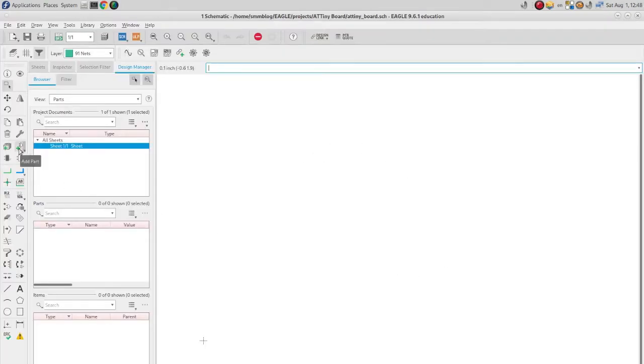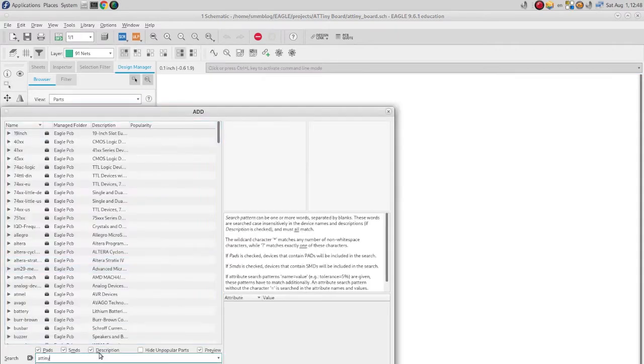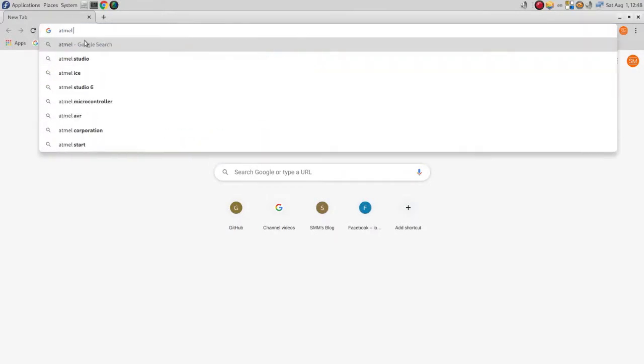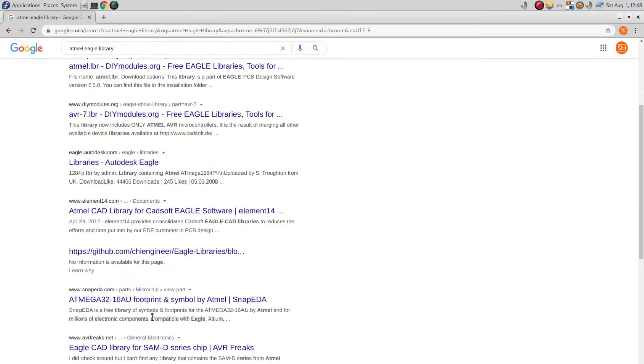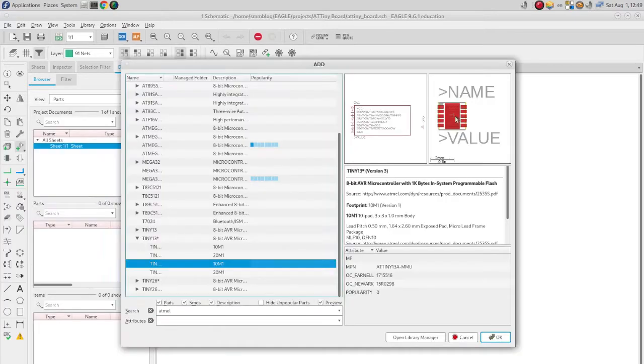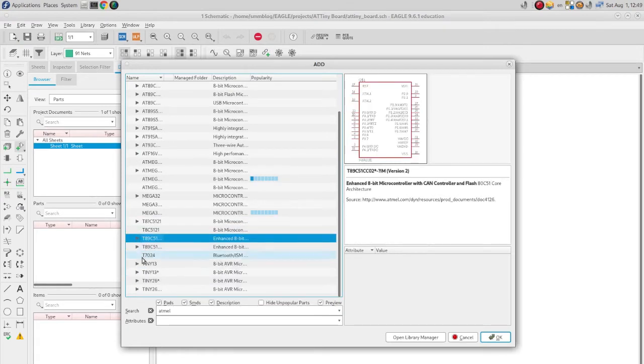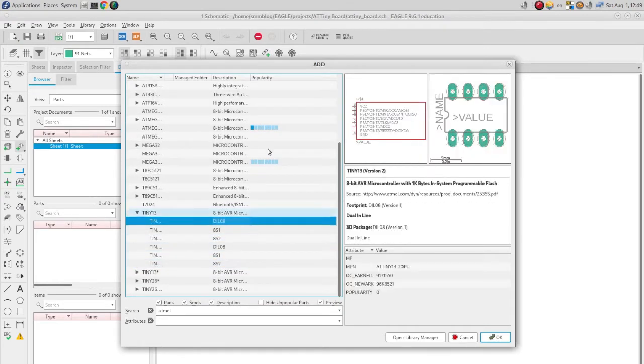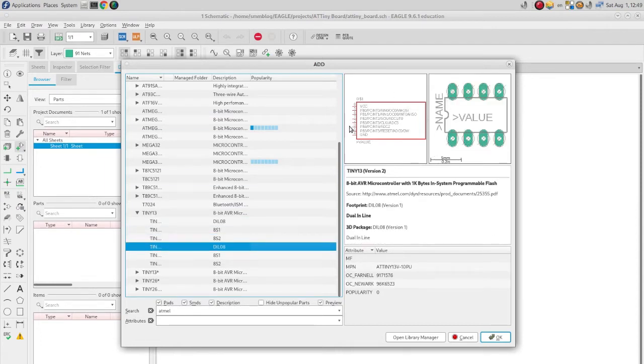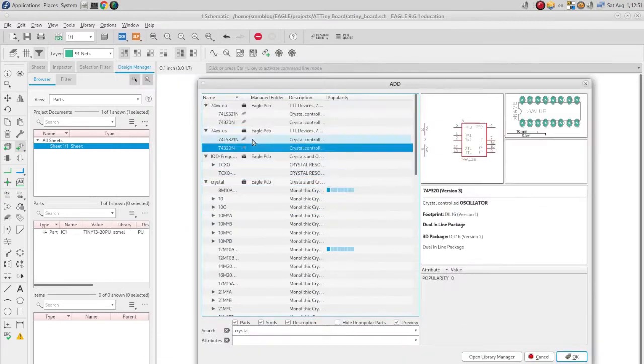The first thing to do while making your schematic is picking the components you want to use, but there is a very important thing, which is when picking a component you should be sure it's the right shape and size. Not talking about the symbol shape, but about its real shape. Here's for example the AT-Tiny13 IC. You can see that there are many shapes and sizes for it. Some are SMD and some are through hole components, so you should be sure about what you are picking because it's important. Then just repeat this process of checking everything for each component you add.